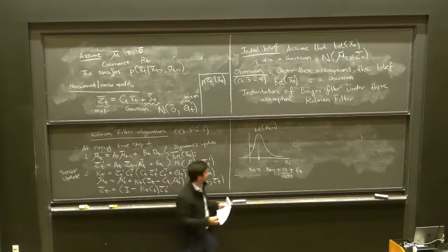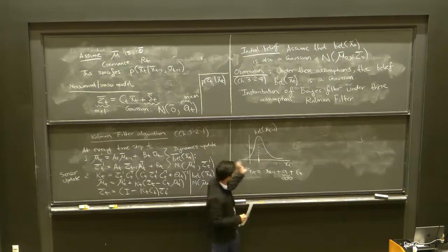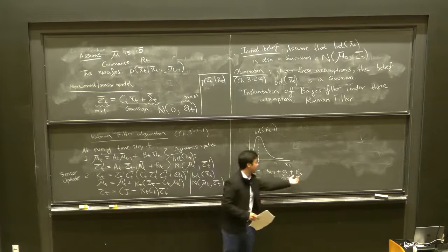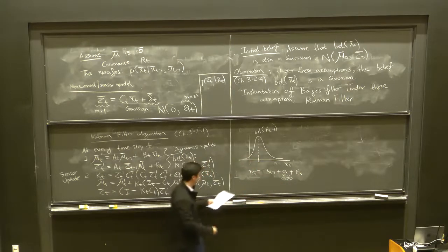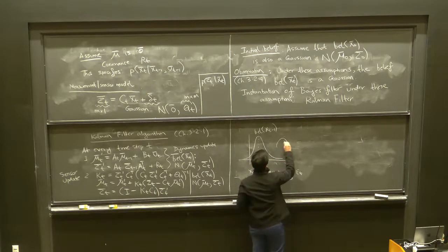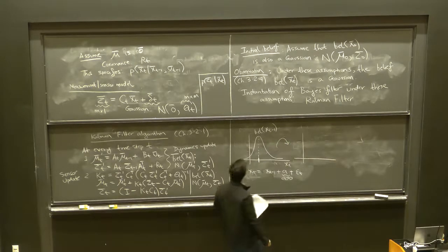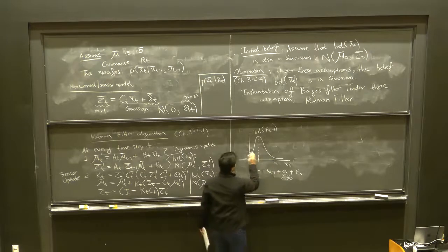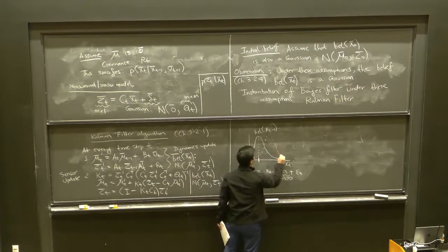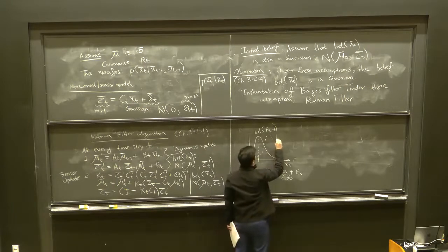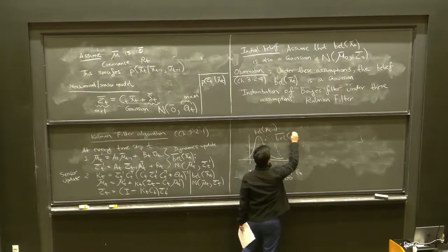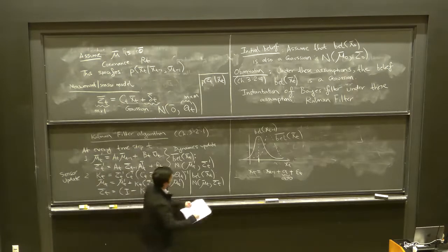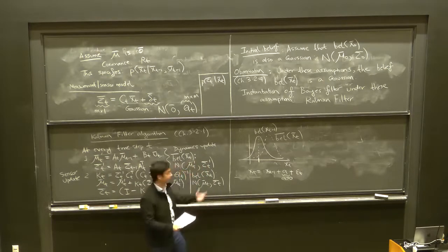Yes, exactly. So we shifted by a. There was no uncertainty here, you literally just shifted by a. But then because we have some uncertainty, it's going to inflate the Gaussian a bit. So we just take this and we shift it. That's going to be belief bar at xt: the belief that we get before we've taken into account a sensor measurement, but after we've propagated the previous belief through the linear dynamics.